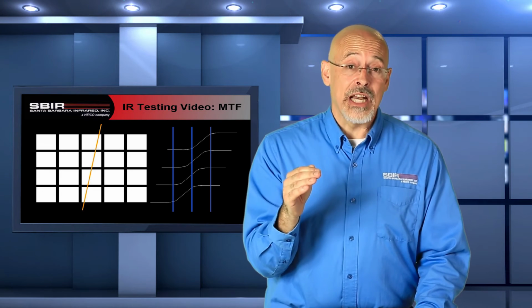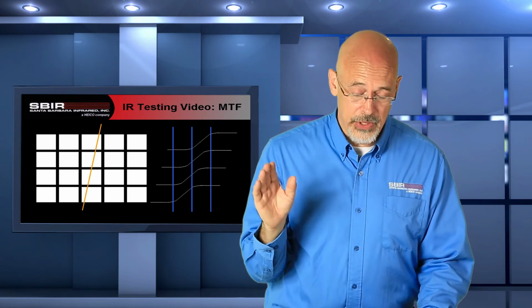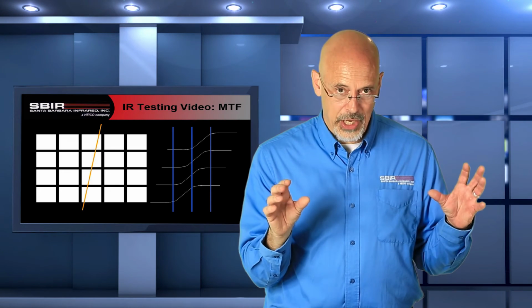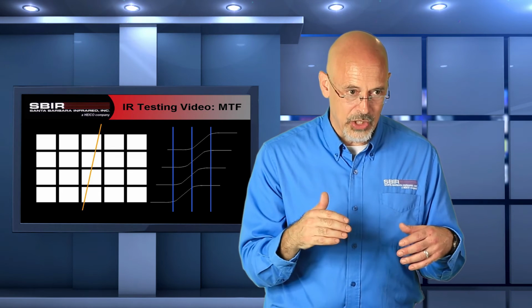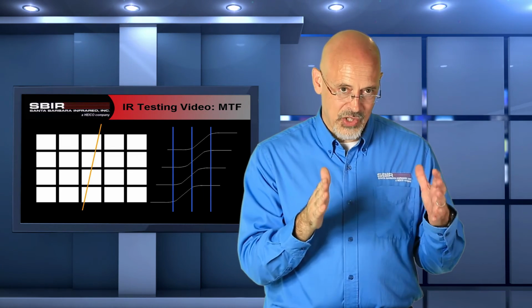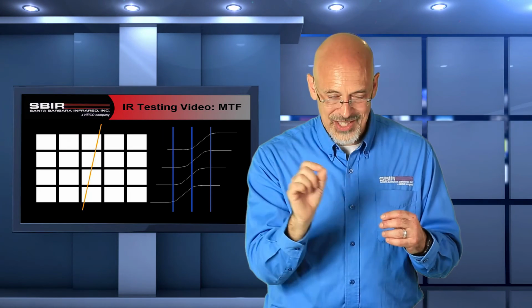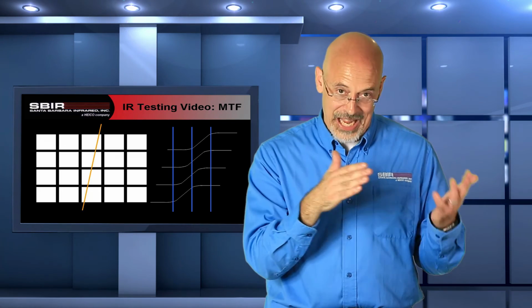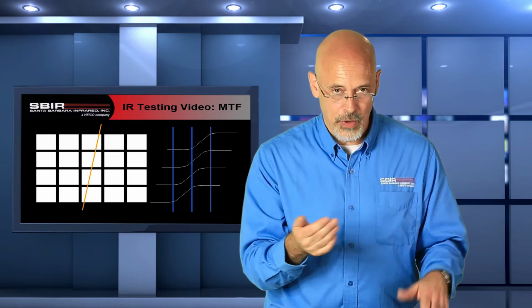And you actually see that a lot. You'll notice in the lower right of this slide that you're looking at, this is a roof line with some tiles on it. And you can see these lines that occur across the image. That's the aliasing that occurs. Your camera is taking a picture at a lower frequency than the tiles that are on that roof, and so you get these fake lines because the aliasing problem makes it look like there's a lower frequency signal.